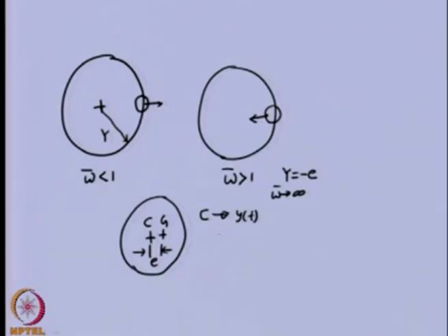If C is displaced by minus E, what is the meaning of that? That means the center of gravity will try to come to the rotational axis of the system. So, the disc will rotate about the center of gravity, and that is why we have this particular low vibration once we cross the critical speed.